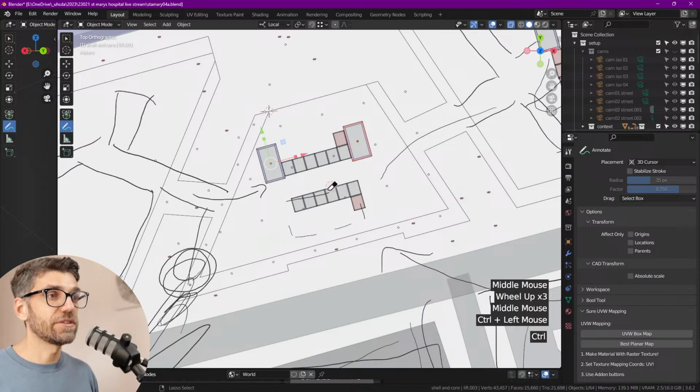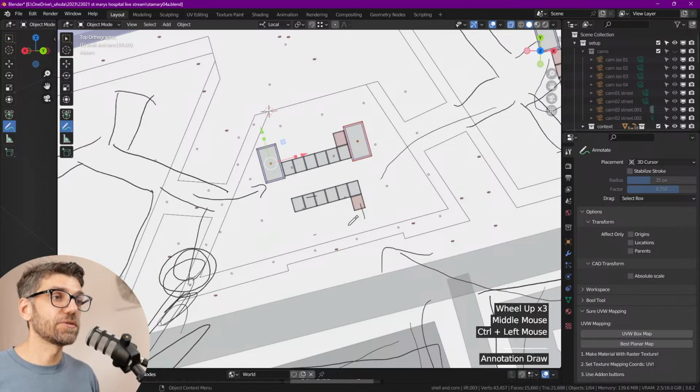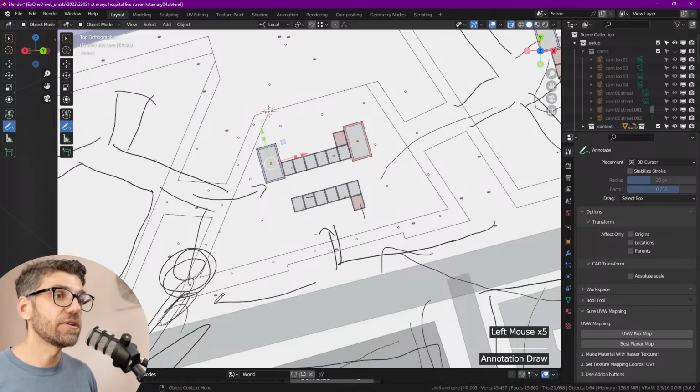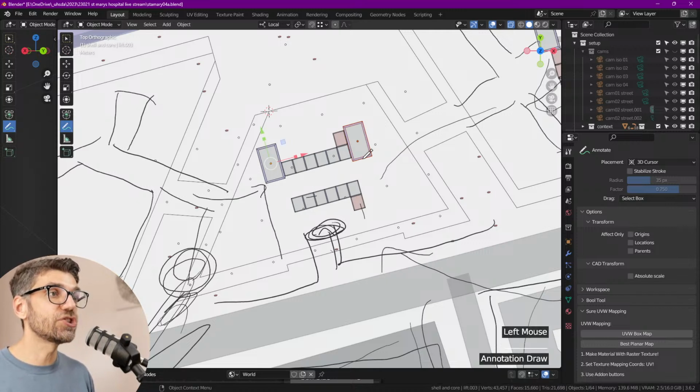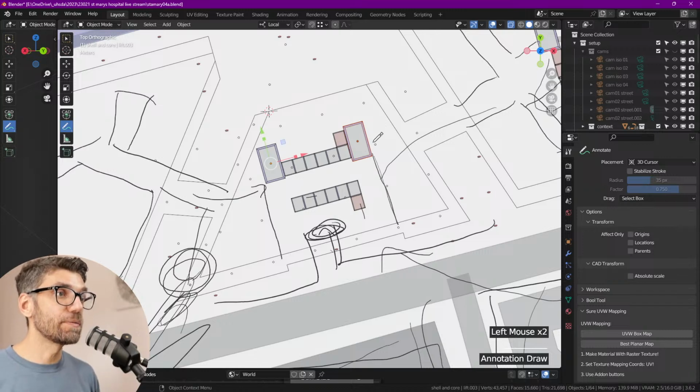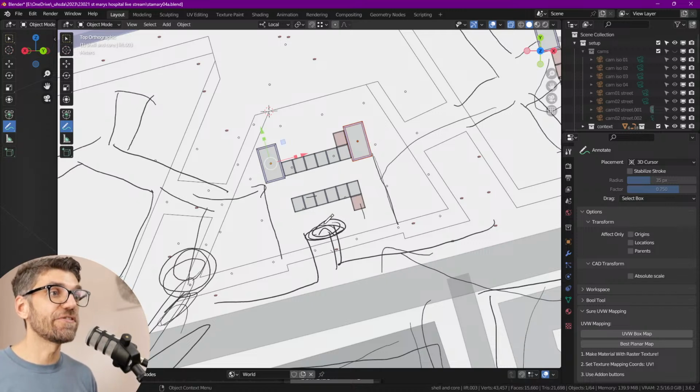Cool. And so from that point, we're going to put the entrance somewhere over here. So you need to walk through there, and you come in there, and then from that point, there has to be a very clear understanding of how you get to the actual core and the ground level. So we usually do that by shaping up that core a little bit more. It should still be a bit more generous, so not too constrained. When you enter, you should have a fair bit of space because, again, there's a lot of people moving with wheelchairs and all kinds of different aspects.